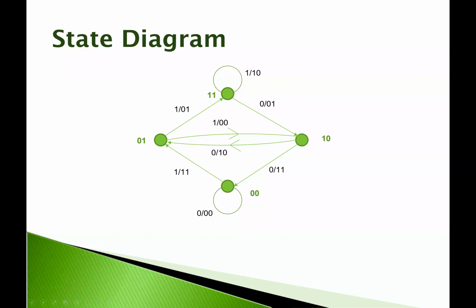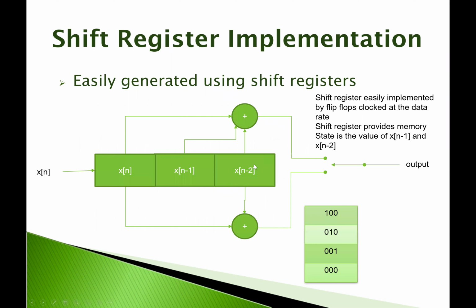We just add a different unique parity equation, and we have another modulo 2 adder outside it, right? So we can use the same shift register structure, but just add another modulo 2 adder, and then we just need a different combination of these bits, maybe xn and xn minus 1, or conversely xn minus 1 and xn minus 2. Probably xn and xn minus 1, so we're capturing that input bit each time.